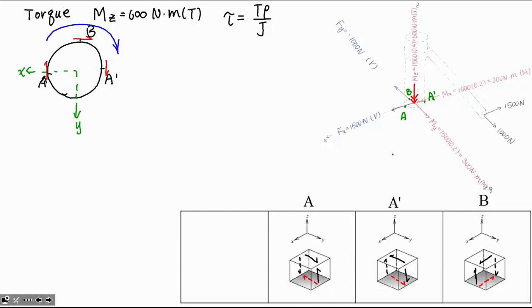So how much is this? We are going to use T rho over J to calculate. So the torque is given, what is the rho? Yes, radius. How could we calculate J? Pi over 4 again? No. J is different. It will be doubled, so pi over 2, r to the fourth.